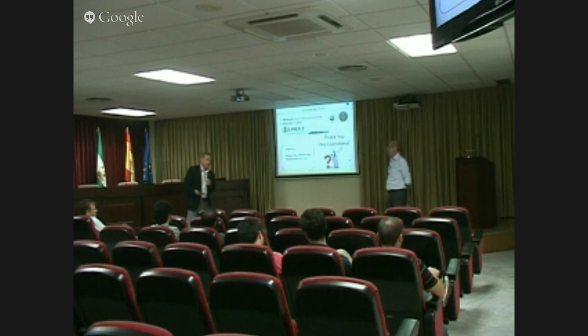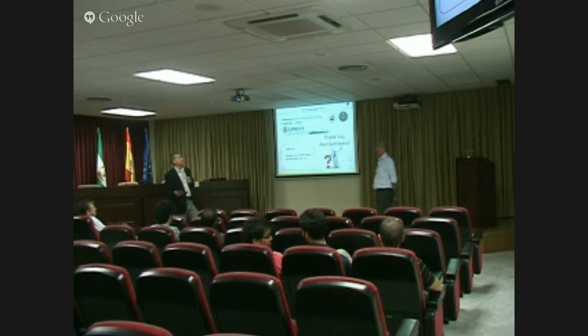Okay, yeah. My question was because what I find really useful and interesting is the distribution case, because in the transmission system, as you know, they have these digital relays, IEDs. And those digital relays, most of them, for instance, Red Eléctrica is adding PMUs just for relaying purposes, not for state estimation. So those IEDs can be immediately connected and report the trip of the line to the control center.